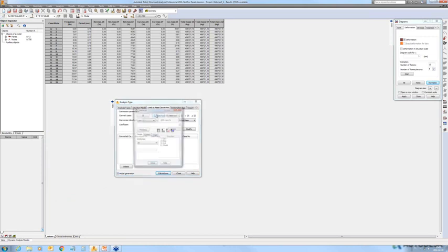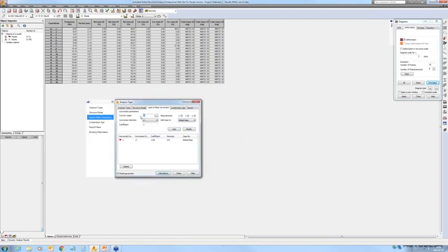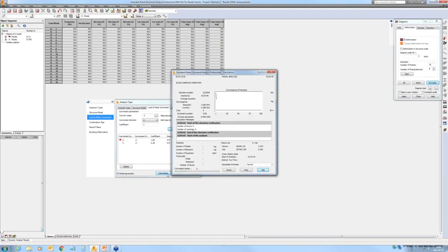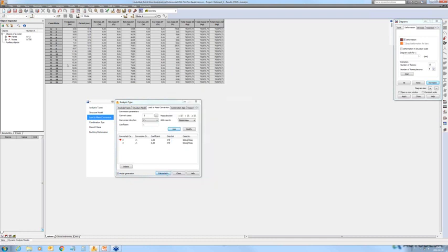So I will convert case 2 into mass with coefficient 1, so all the load is going to be treated as mass. And for case 3, I will convert only 30%. Now, if we calculate the model, we can see the change in the frequency. The frequency is now lower than it used to be before. Let me go back to the presentation.